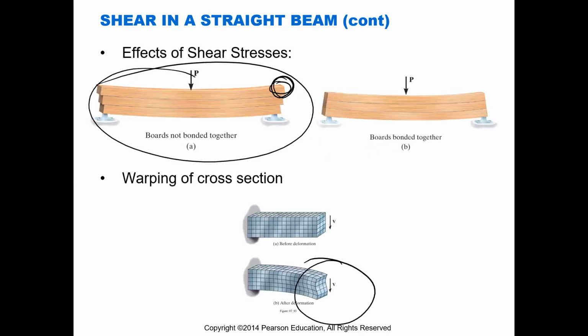It means that we assume that plane sections remain plane, so we don't concern ourselves with... Well, that's what warping means? Yeah, so warping means that this cross-section doesn't stay the same cross-sectional shape and it doesn't all move perpendicular to your longitudinal axis.